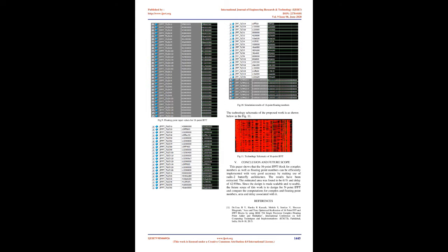AR, AJ, BR, BJ are the real and imaginary parts of the inputs A and B respectively. Also, C and D are outputs with their real and imaginary parts as shown in equations 3 and 4. In Fig. 1, A and B indicate the complex input from the preceding stage, while C and D indicate the complex output of the present stage, or the complex input to the subsequent stage. The twiddle factors Wn are defined as the coefficients which are used to compute results from the preceding stage and to get inputs to the next stages of the IFFT algorithm. The only difference between the butterfly of FFT and IFFT is the position of the twiddle factor, which can be seen from Fig. 1.